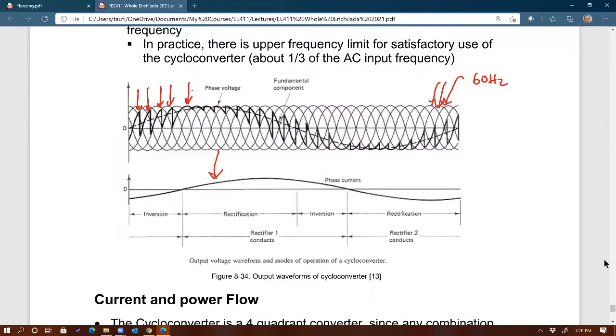Okay, clever. Professor, can you go from single phase to three phase with this by just paralleling three and altering the phase by changing alpha for each of the bridges? I think so. You just have to introduce a phase shifting transformer. That's one way to do it. Yes, they do exist. Also, you can time the control like you are suggesting. That could be done too. Does that answer your question?